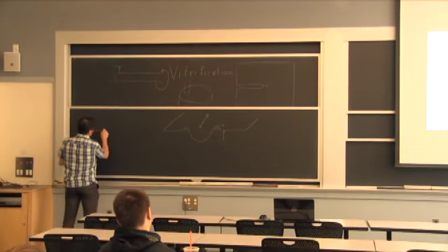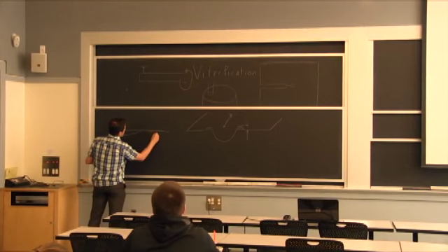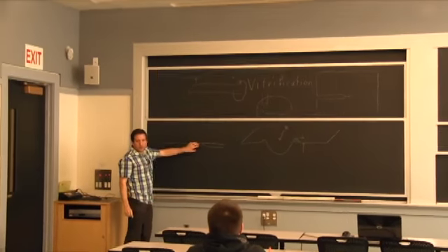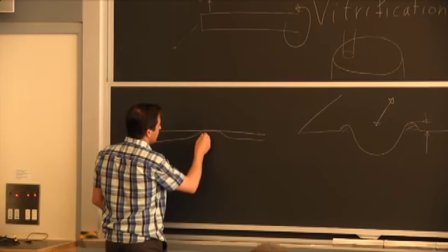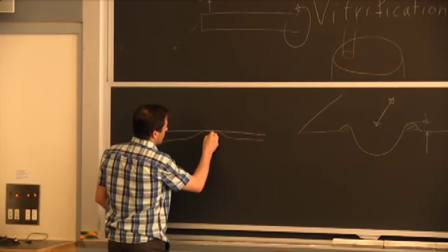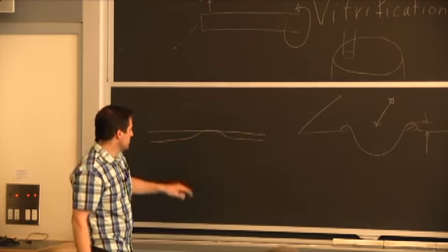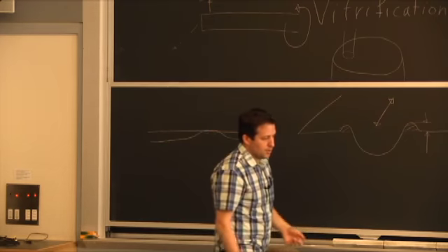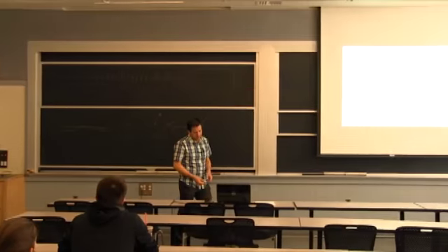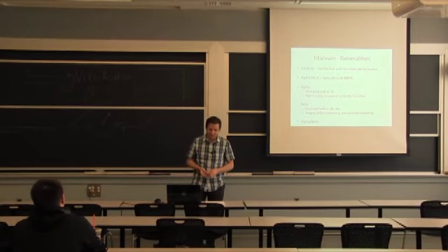Say I have two surfaces, and then they're not perfectly flat. So there's always going to be one area that's preferentially contacting. And then if you happen to bind here and break at another location, now you have two surfaces. This surface is not flat anymore. So you're roughening the surfaces, and you have accelerated wear. So it's a situation you want to really avoid, and I've seen it a lot of times.